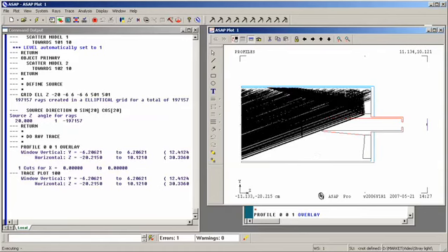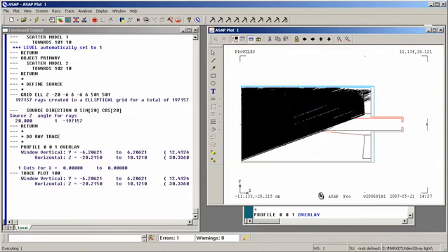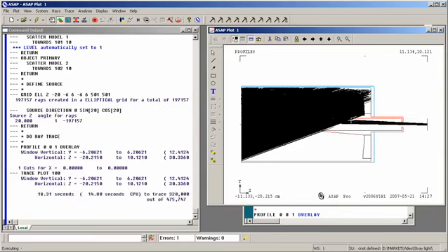Here's our ray trace. We can see that some of the light is indeed illuminating the primary mirror. When ASAP is finished tracing the parent rays, it generates the scattered rays from the primary mirror, which we see here. We're also going to be generating scattered rays from the inner conical baffle. Those are the same rays that we saw before.